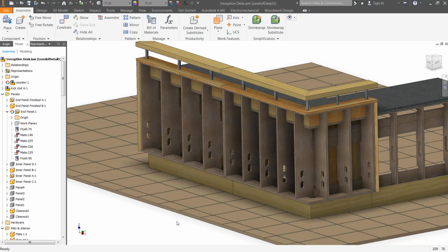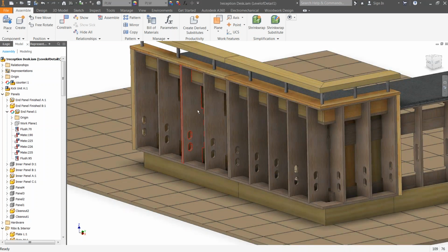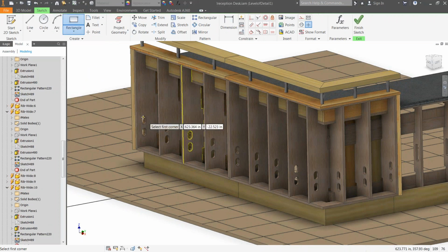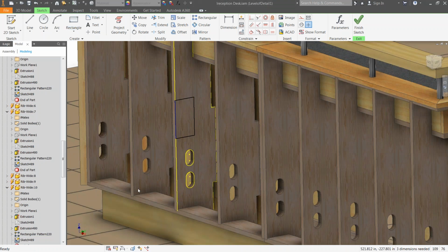But again, because maybe I didn't start that way, I'm limited if I'm not using tools like this. So I'm going to create a slot or a groove here and then create a horizontal rib on the fly. To accomplish something like that, it's kind of simple. All I'm going to do is sketch on it, and this time I'll draw a rectangle starting from the edge and just opening it up like so.